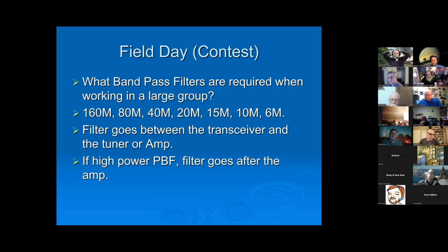And also on the receive side, it keeps us from receiving a bunch of extra high-powered garbage that may end up affecting our receiver. So when we do contesting, it's always on 160, 80, 40, 20, 15, 10, and 6. 6 is sometimes optional depending on the contest.